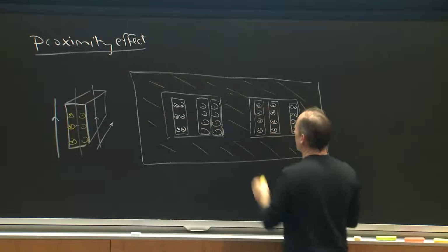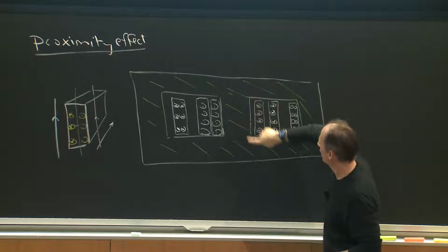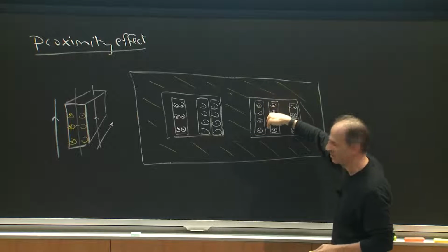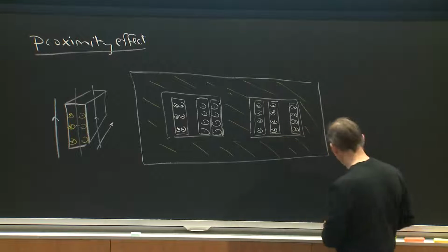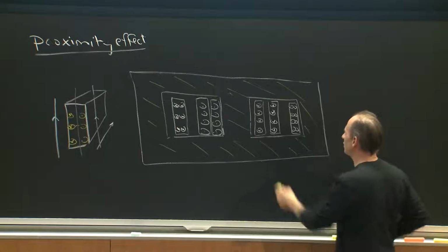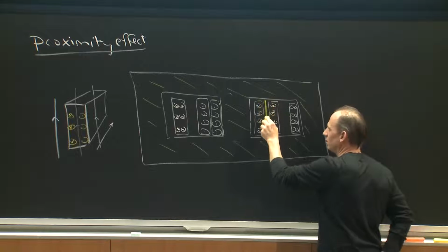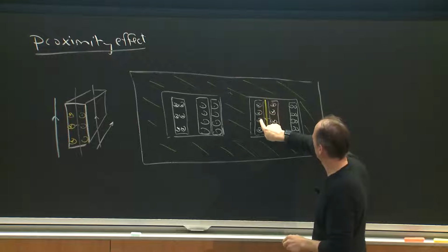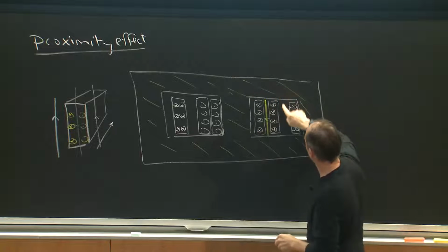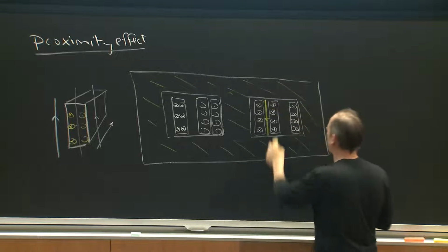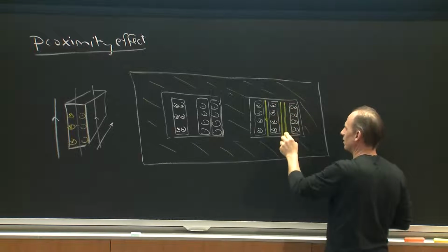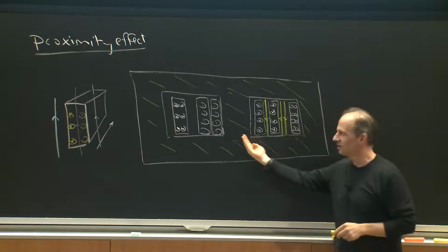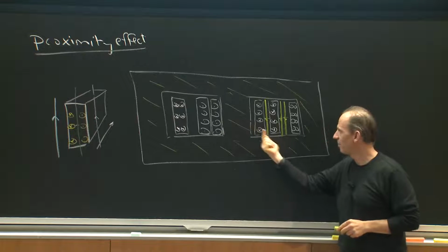So if I execute Ampere's law, integral of H dot dl around, say, a loop here, the only field that appears is in the window. And what that means is, in this picture, if I plotted the H field, I ought to have some H field here that's associated with this current from the middle. And if I looped around 2 layers of winding, I get 2 H fields, and so forth. So what's happening is I go across the window, my field builds up.